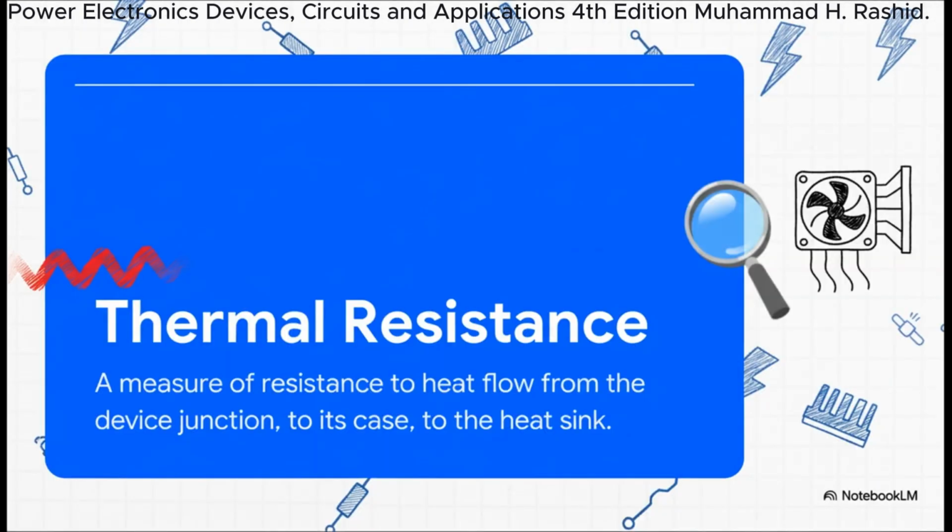So how do we manage all this heat? Well, first, we have to understand its journey out of the device. And we do that with a concept called thermal resistance. Just think of it like resistance to heat flow. It's a series of roadblocks. You've got one barrier from the tiny silicon chip itself, we call that the junction, to the plastic or metal case. Then another from the case to the heat sink you bolted onto. And then a final one from the heat sink out into the air. Our job is to make that whole path as easy as possible, to lower the total resistance.